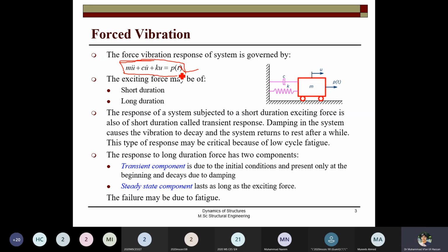there are two kinds of frequencies. One is the frequency of the force and the other is the frequency of the system. It means that we have to see also the response of the system as a function of the time, like a seismic loading or machine loading, like any other loading. We must know what is the behavior of the force with respect to the time that we apply to the building. And this is called the time history analysis of the building.